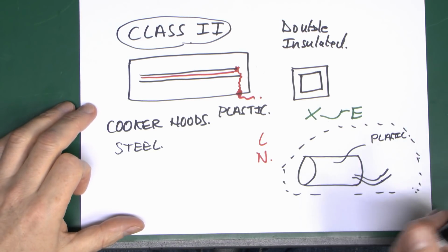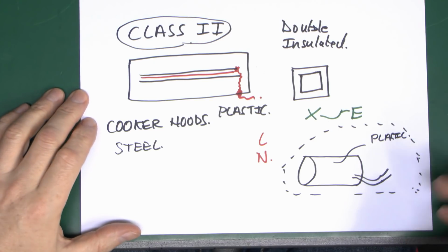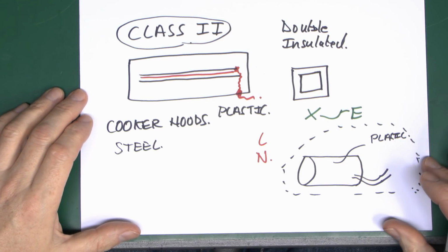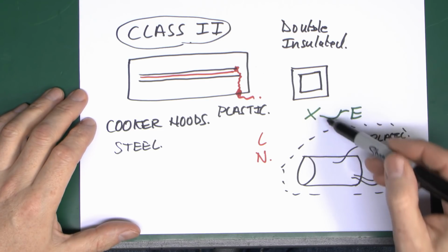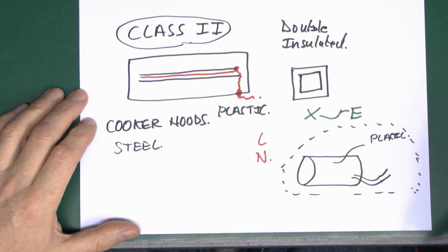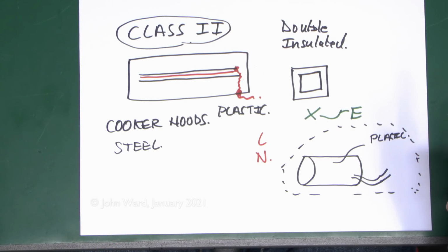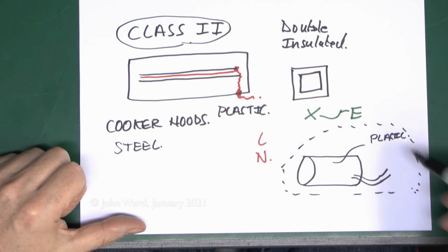So the outside metal bit is just sitting there, it's not connected to anything, it's not effectively even part of the electrical installation. If you then decided for some reason to connect the protective conductor to the metal casing, what you then got is a huge big slab of metal which is now connected to the electrical earth, which isn't really desirable, because if someone grabs hold of that and touches something else like a class 1 appliance, there's a fault in that one. You've now got a nice handy path to earth through somebody's body, holding one in each hand, so you've actually made that situation worse.